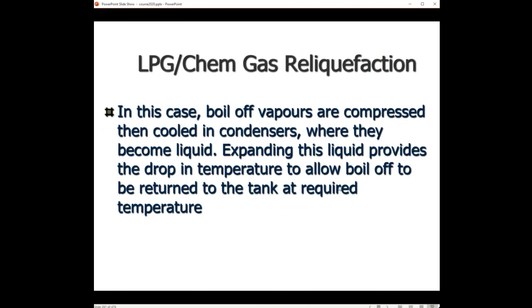Okay, the reliquefaction plant, there the goal is to take away the boil-off. That is the main goal. Since by taking away the vapors from the tank, you in fact also take away the heat of the tank. Because if there is heat ingress through the insulation and cargo liquid is evaporated, the vapors are containing the heat. Because the liquid is still at its boiling temperature. That does not change. It will remain at its boiling temperature.